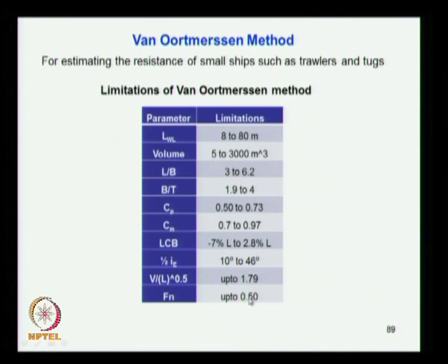So if the vessel which you consider falls within this range, and the type of vessel is also the same as trawlers or tugs or small crafts, then naturally you can try this method for the estimation of resistance in the preliminary stages of the ship design.